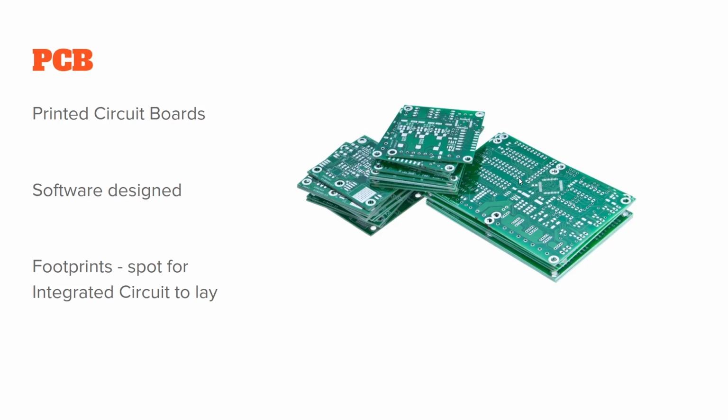I keep bringing up this solder. I promise I'll talk about it in a second. Solder that on, and there's also these little white pads with no holes inside of them. These are what's called footprints. Footprints is basically where a component is going to go. These are footprints for the ICs that are surface mount. So we would solder those onto these footprints, and that would give us a more permanent solution to our breadboard alternatives.